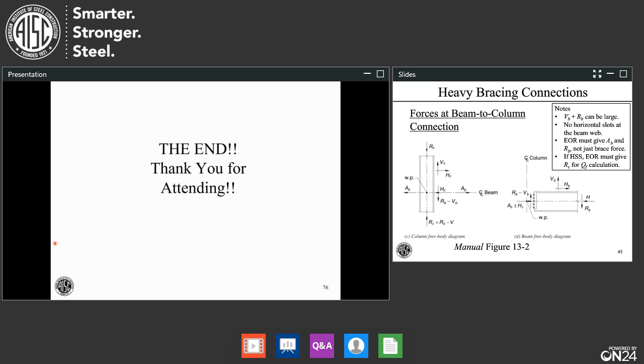I think I just wouldn't do that. I guess if you had just an absolutely completely trivial connection, maybe it doesn't matter much there. But anything other than that, I'm probably not going to do that. And if I needed to establish the strength, I'm trying to think how would one even go about doing that. I guess you have block shear there. That's going to be very, very weak if you only have one bolt, because the A sub N V, the net area subject to shear, is going to be really small.